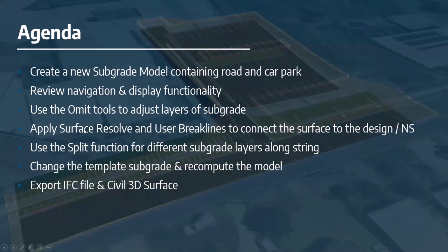We'll apply something called a surface resolve, which is effectively like a batter. It's all very well having a subgrade surface, but how do you reconnect that subgrade surface up to, for example, the natural, or maybe up to the design? So we're going to be looking at the surface resolve tool and the user breakline tool, where you can pretty much just add in your own linear breakline into the design. We'll also look at the split function, which allows you to break a string and tell it to do something else,